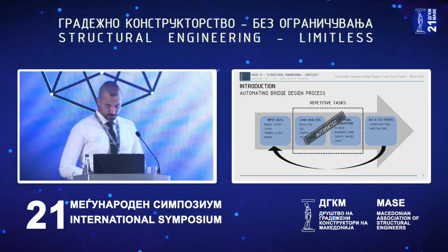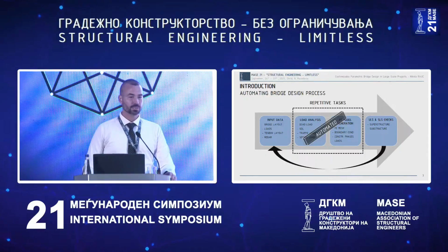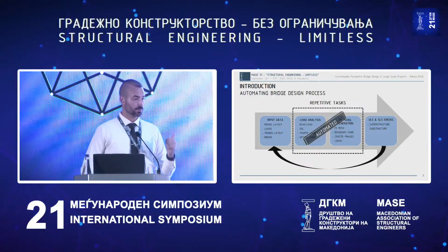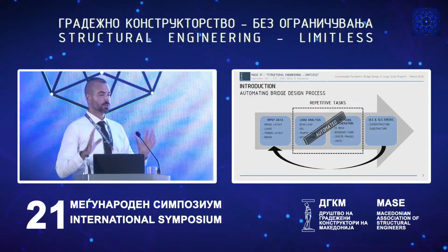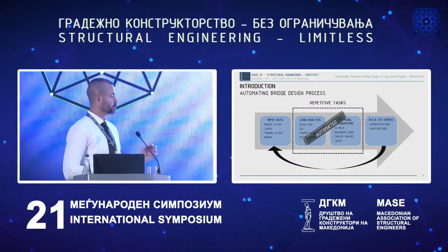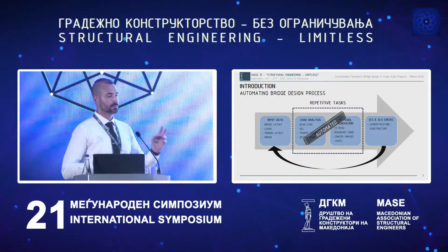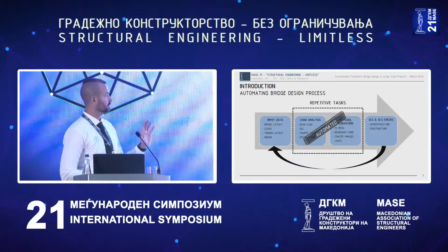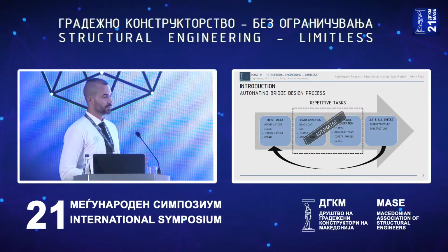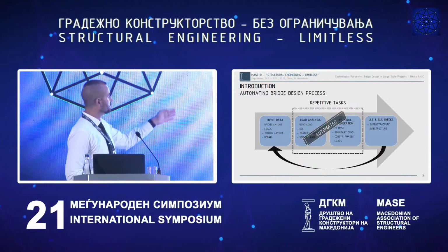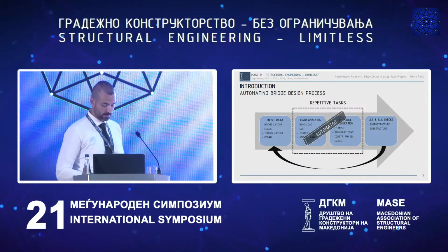So if we manage to automate the second and the third step, the only thing that we are dealing with is the first step. We conceptually look at the bridge. We deal with how our tendon layout should look. Then someone else does the second and third step for us, and we just check whether the ULS and SLS checks for our super and substructure pass or not. If they do not pass, we just change the initial data, and these second and third steps are automated.